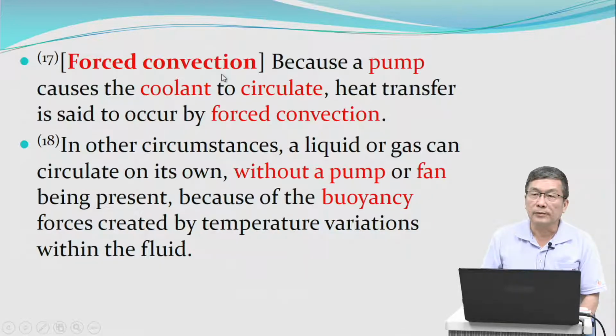Forced convection. Because a pump causes the coolant to circulate, heat transfer is said to occur by forced convection. In other circumstances, a liquid or gas can circulate on its own, without a pump or a fan being present, because of the buoyancy force created by temperature variations within the fluid.